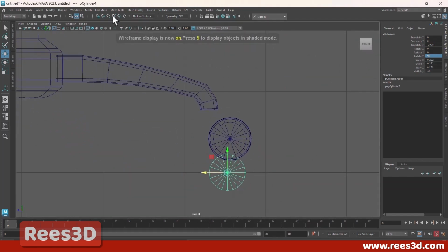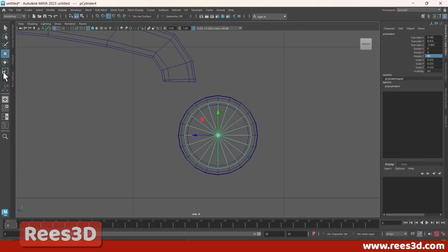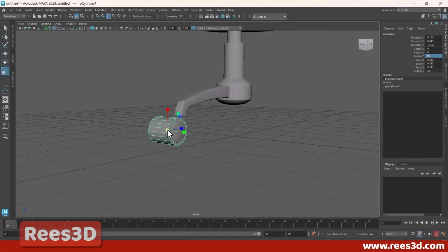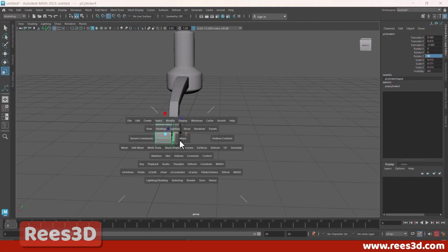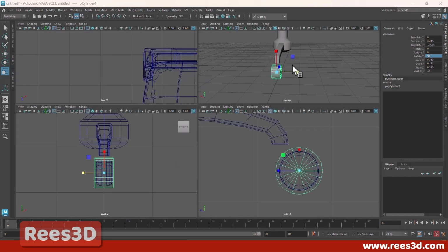We can use something called a point snap here. So if you see this magnet with a small point, I can actually snap it to any of these points so that it stays exactly in the center. So that's what we want. And I can make it a bit bigger here to encompass this entire shape. Make it a bit smaller. And now to put them exactly in the center, I can use the grid snap. There you go. Let's make it a bit bigger to cover up that entire space.